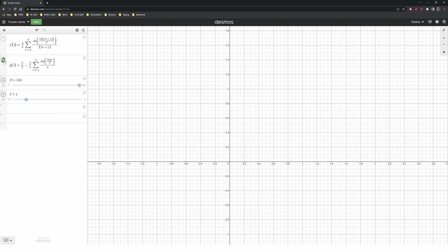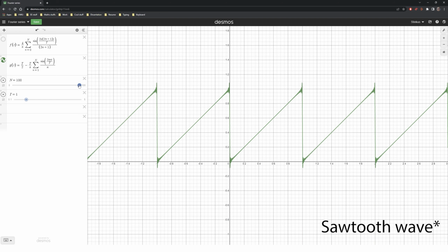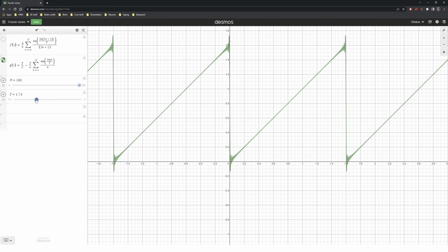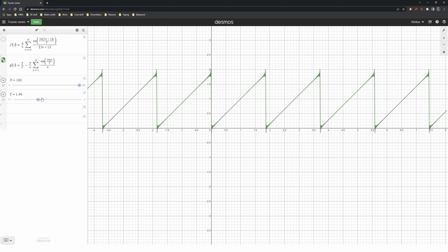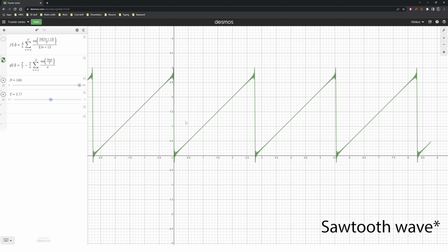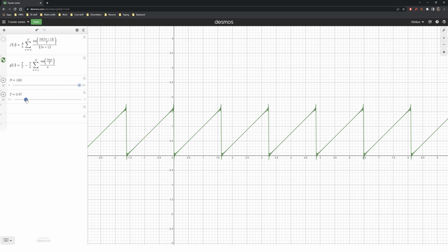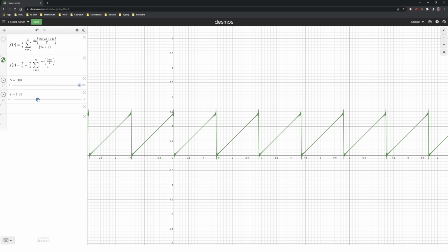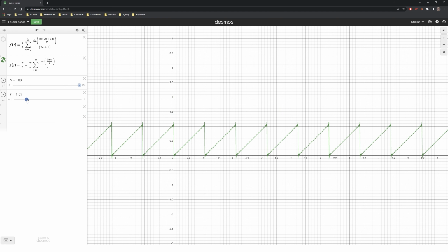Let's now look at the other example, which is a triangular wave. And this triangular wave, you'll notice, has the same Gibbs phenomenon at the discontinuities. And if I increase the period, you'll also see that the height increases just as I said. Because again, the triangular wave is dependent on the period because it is just equal to t. It is just a steady linear ramp for the entire time that it is defined. And thus, it varies with the period.